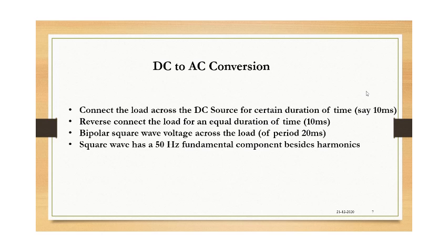So then what can you expect at the output? You may expect at the load you will have positive voltage for 10 milliseconds and negative voltage for 10 milliseconds. So for one complete cycle, you will get a square wave at the load.